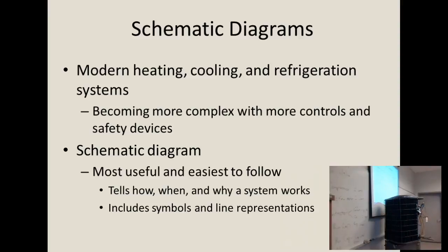Step 2. T1 to the motor commons. How many motors do we have? One inside the compressor and one for the condenser fan motor. Do y'all remember the symbol for a split phase motor? Told y'all that first test of symbols. That's a motor, right? Compressor, condenser fan.